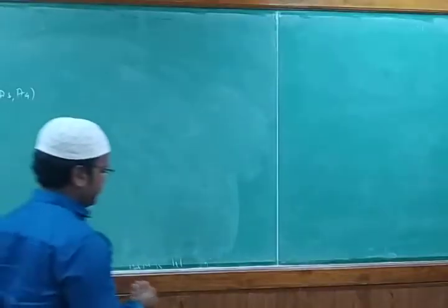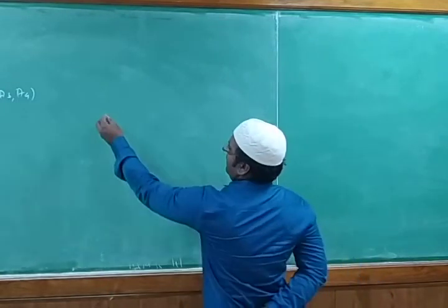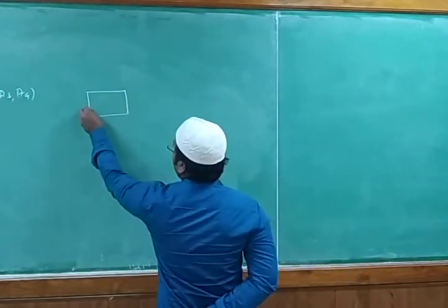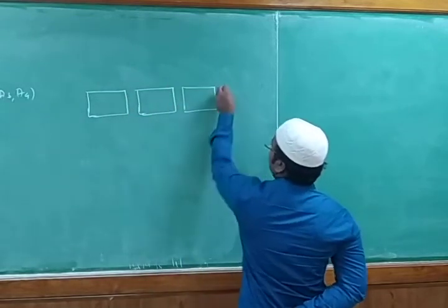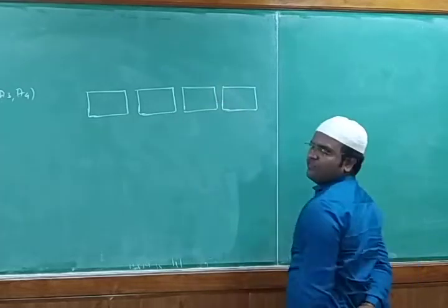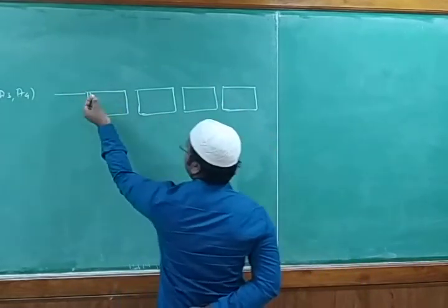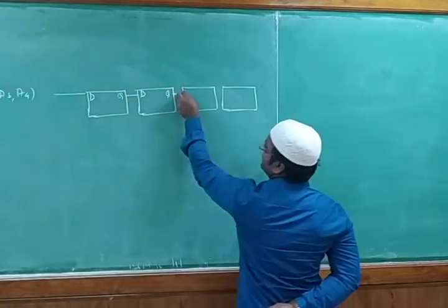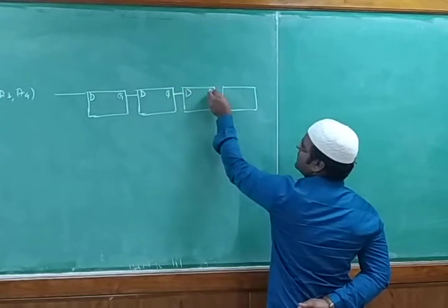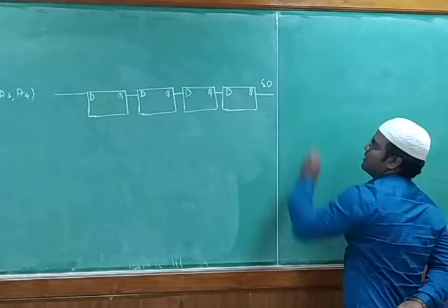So students, the next way we can design this D flip-flop for 4 registers is by using serial in and serial out. How do we get that? We can connect 4 D flip-flops serially like this, right? So we can give the common input, I0, I1 become now common for D. The output Q will be passed to the input of the next one, and the output of the next is passed to the input of the next one, and the output here is SO, that is serial out.